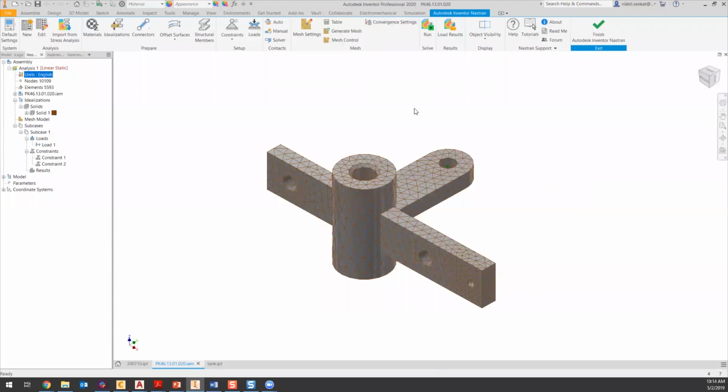In general, the finer the mesh, the better and more accurate the solution. But there does come a point when refining the mesh further doesn't change the solution at all, or doesn't change it significantly. At that point, your result is a mesh independent solution. And that's what we're going for, right?